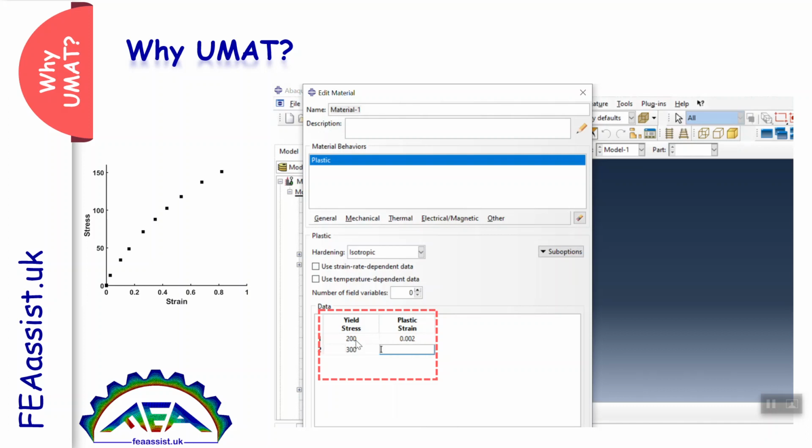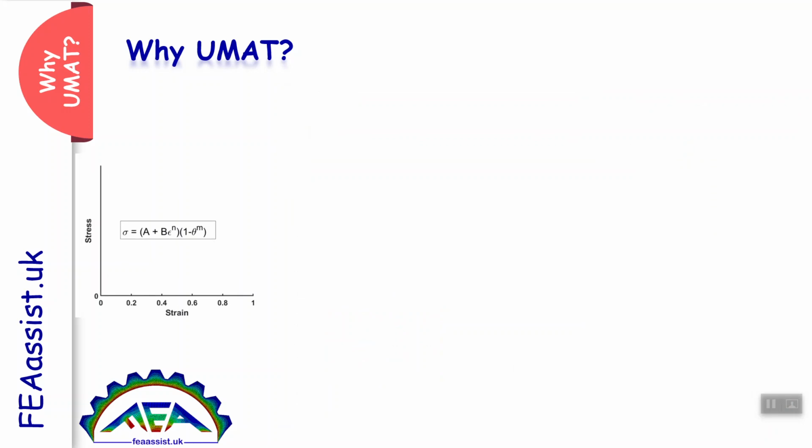This is the simplest way of solving the problem, but it is not precise because Abaqus interpolates between these points and solves the problem in all points. If you want to solve your problem more precisely, then you need to have a constitutive equation, a constitutive behavior for your material. An equation in which the stress is a function of strain, temperature, and strain rate. In this example, we have a material that obeys this equation, which is the Johnson-Cook equation.